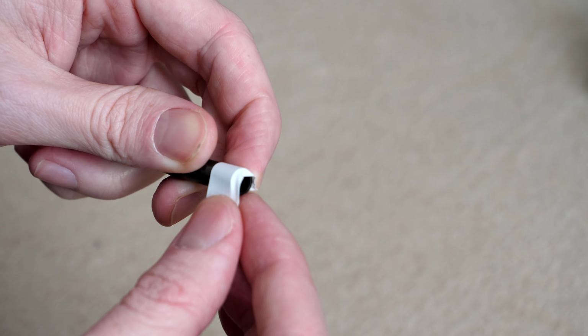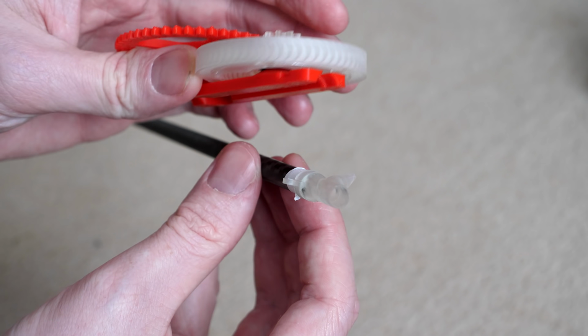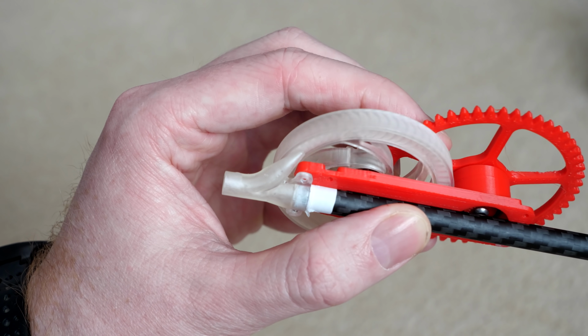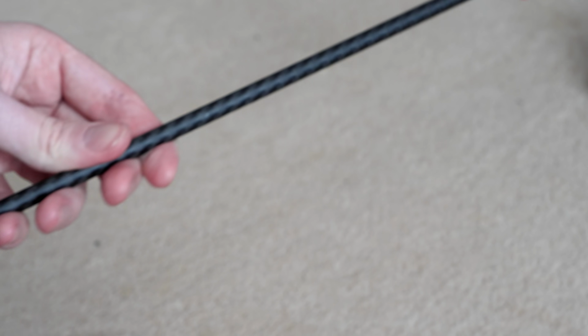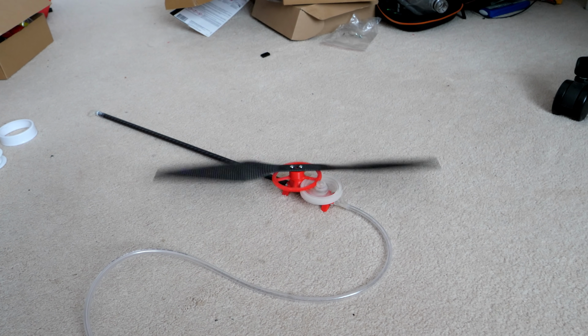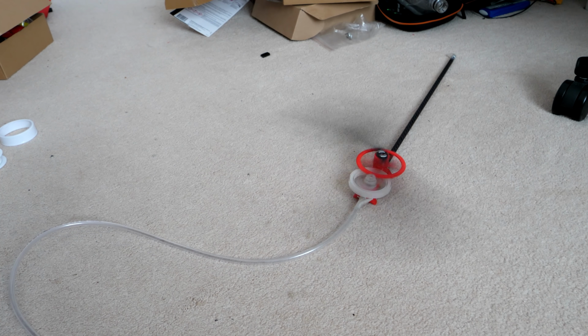At the turbine end of the tube, I designed a 3-way fitting that allows the incoming air to pressurise the tail boom, but also acts as a nozzle to power the turbine. Then at the other end of the tube, I can mount a 90-degree nozzle which will act as a tail rotor. With the propeller and air supply attached, I can spin the turbine and see how the torque compensation works.